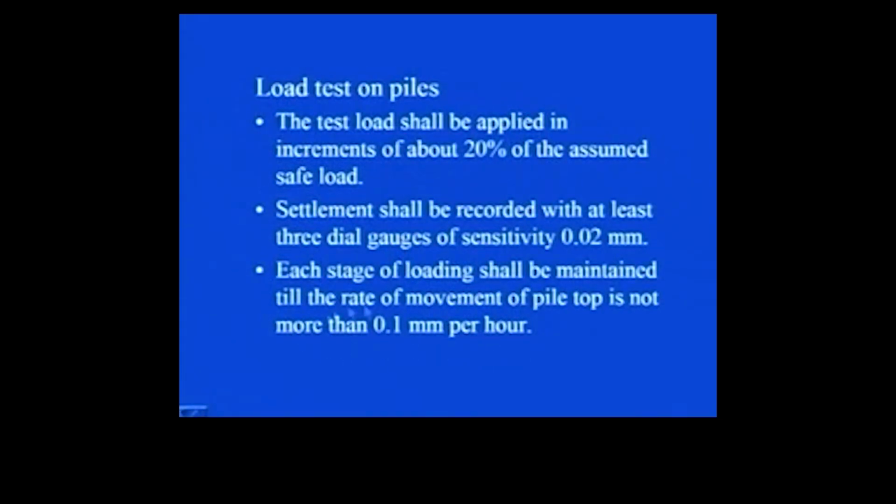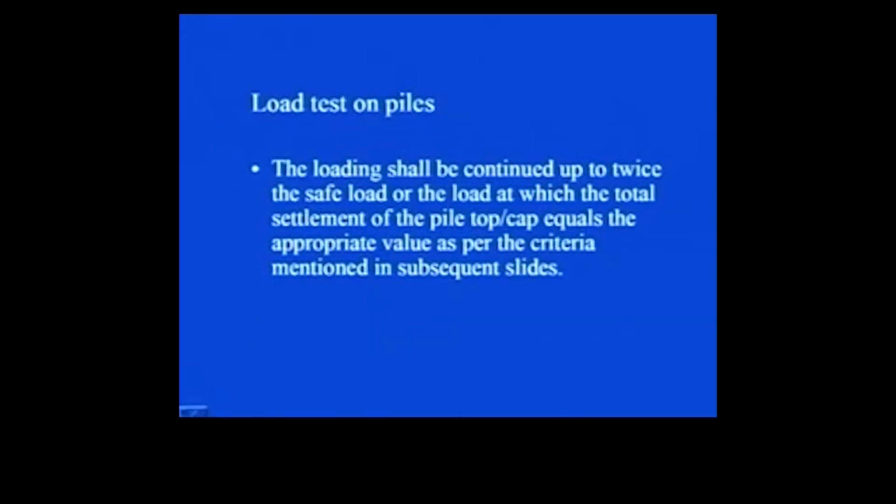As long as it is more than 0.1 millimeter per hour, you have to keep on waiting after applying that particular load increment. Then the loading shall be continued up to twice the safe load, or the load at which the total settlement of the pile top or cap equals the appropriate value as per the criteria mentioned in the subsequent slides.